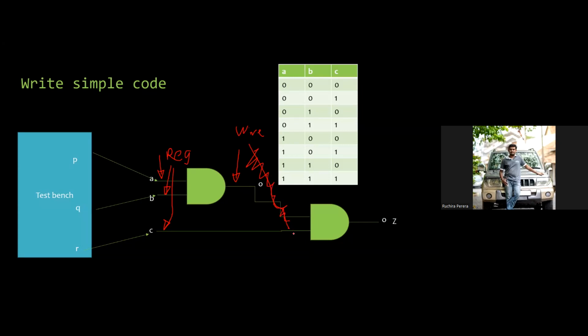Oh no, this is not a wire. I'm going to leave it like this. This is the wire. You will be defining your variables like this: these 3 registers and these 2 wires, and then you will create this test bench. If you are trying to do this one, please try to get a screenshot of this example that I am showing on the screen right now.